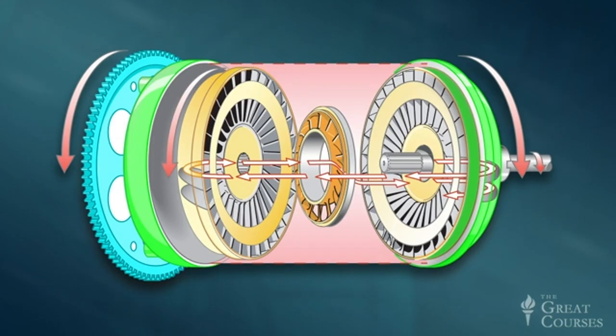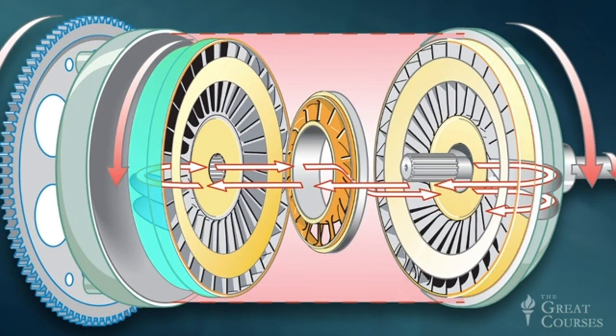Thus, whenever the engine is running, the impeller rotates at the same speed. The turbine forms the other half of the donut and also incorporates a set of curved vanes. The turbine is contained within the torque converter's housing, but it can rotate independently. Its shaft extends out to the rear, where it serves as the input shaft to the transmission gear unit.